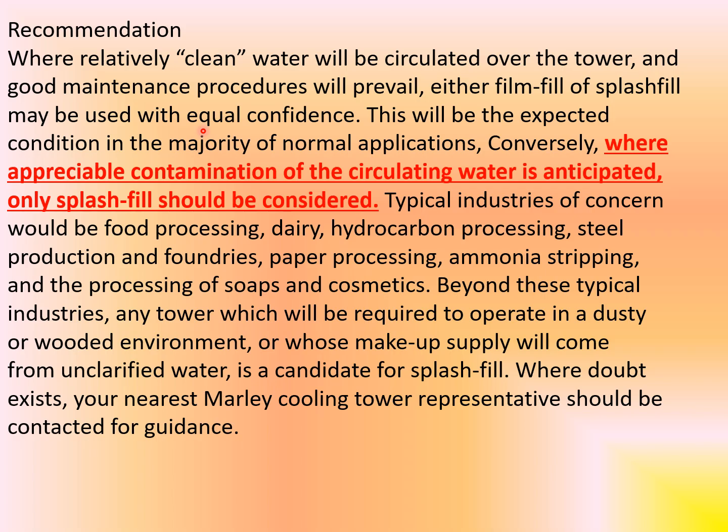Conversely, where appreciable contamination of the circulating water is anticipated, only splash fill should be considered. Typical industries of concern would be food processing, dairy, hydrocarbon processing, steel production and foundries, paper processing, ammonia stripping, and processing of soaps and cosmetics.